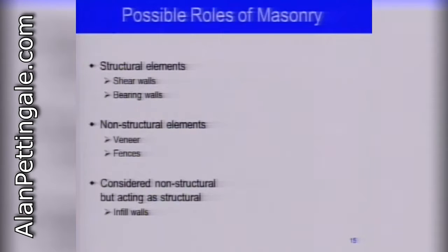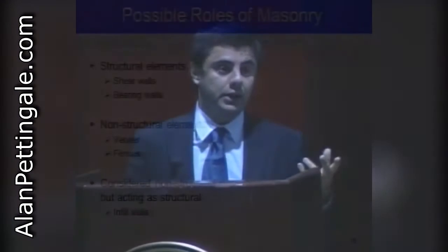So usually for all the structures that were built in the 20s or even earlier, and there are lots of them in California and also around the world, you see people designing the frame without accounting for the masonry. So they design as if the masonry is not there. Turns out that the masonry, not only is it there, but it really makes a difference on the behavior. And that's something that people didn't understand until very recently.